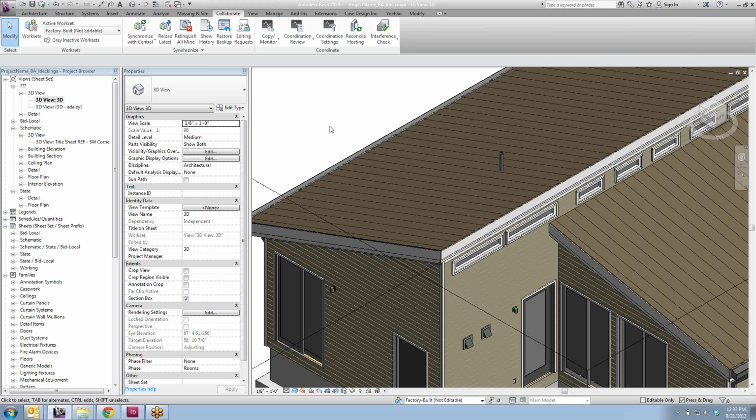Like if we say, look, this is the way that we're modeling our roof, we're not accounting for this extra 2 inches as is shown in the detail, is that okay with you? Or just inform them that they need to put an extra 1 or 2% in their waste factor to cover what's not being modeled. But that granular level of procurement design coordination has never been worked out. But for this, I think it's small enough that it's probably not going to make a difference.